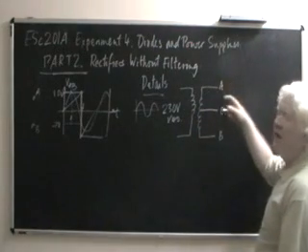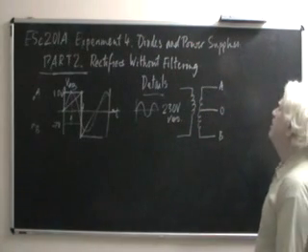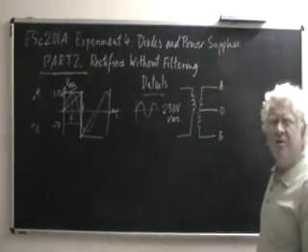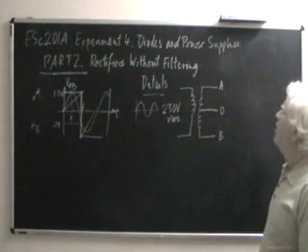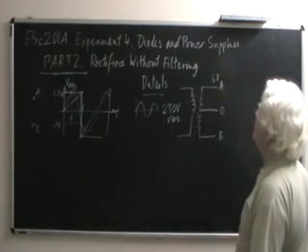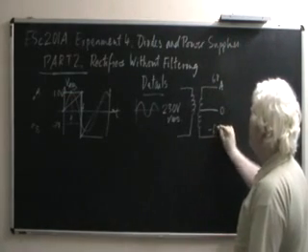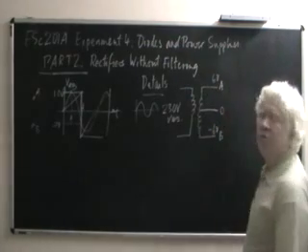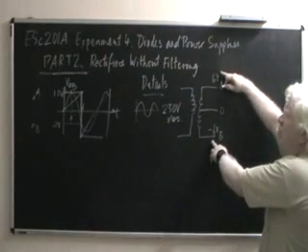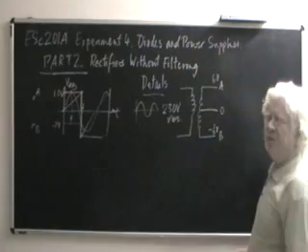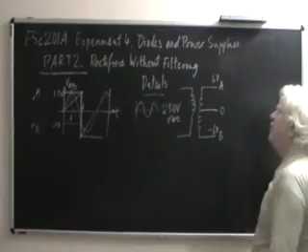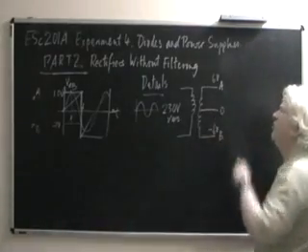So, you can choose to ground any point you like. But the main purpose of this transformer is to step down 230 volts to approximately 1/10 of that value. In fact, 1/20th of that value, so that you get around 6 volts here, minus 6 volts here, with respect to the 0. If you make this the reference, then A will have plus 12 volts with respect to B. If you make A the reference, then B will have minus 12 volts with respect to A and minus 6 volts with respect to this O point.